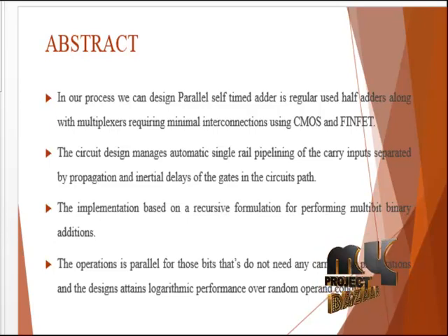These dual-rail signals can be represented in more than two logic values, and therefore they can be used to generate bit-level acknowledgements when a bit operation is completed. Finally, computation completion is sensed when all bit acknowledgement signals receive high values. This carry completion sensing is used in our example pipeline adder, which uses full adder functional blocks adapted for dual-rail carries. On the other hand, the completion in the proposed design uses so-called logic and early completion, instead of fixed delay lines.